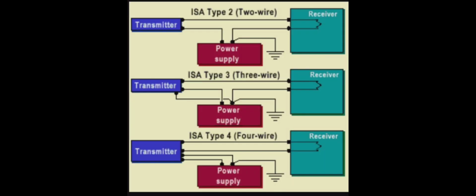So what does two wire mean? The current and voltage are on the same plus and minus wires. Normally it is referred to as loop powered. That means there are two wires. What does three wire mean? A common 24-volt DC power supply is used for both the transmitter sensors and the 4 to 20 milliampere current signals. It means the 24-volt DC power is common.